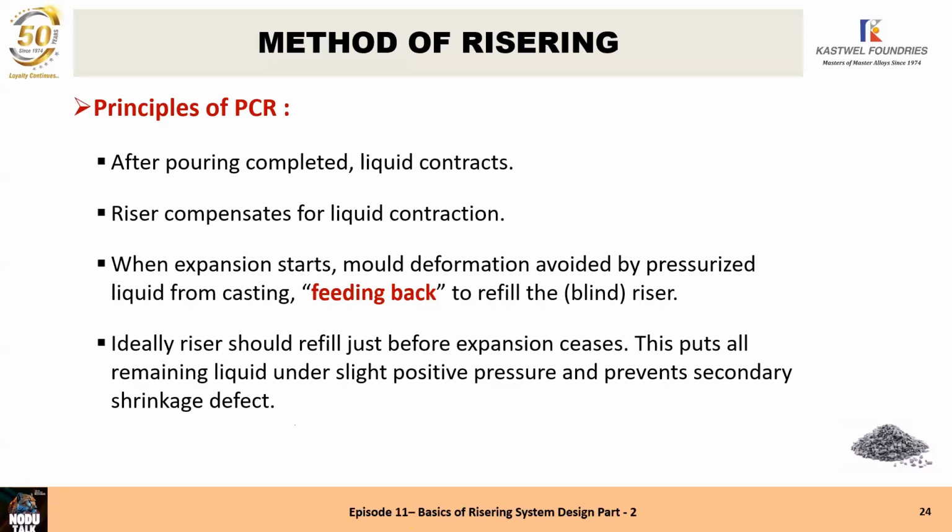So the riser will receive the expanding liquid metal, and the pressure on the mold wall will reduce. We have seen the mold wall pressure can be as much as 2 megapascal. So ideally, the riser should refill just before expansion stops. When the riser refills just before the expansion stops, there's some expansion still to take place.